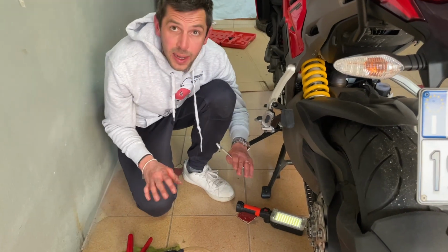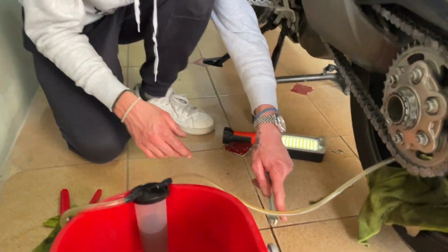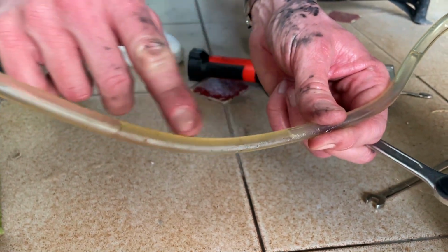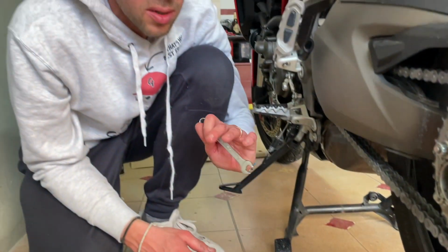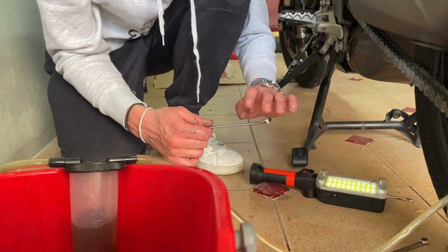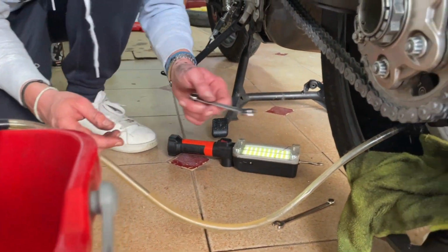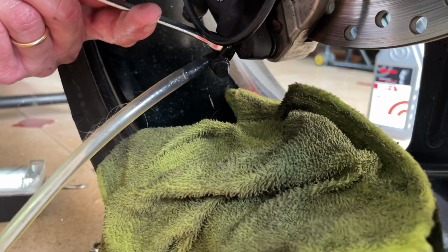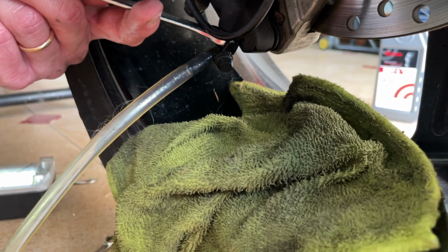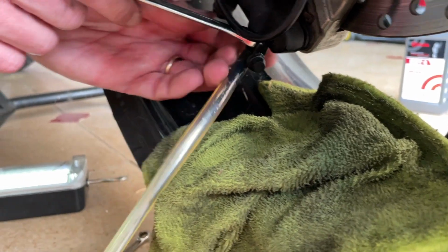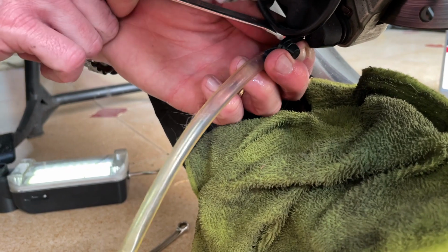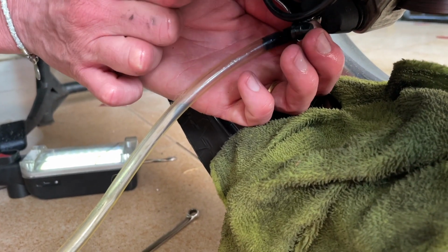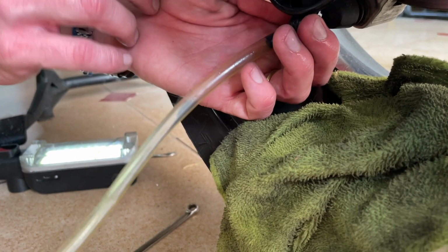Now let's have the final touch. We bled all the system, so as you can see, the oil in the pipe is the new one, so it means that we have flushed the entire system. And now for the final touch, just to secure all the bubbles are out, we will do something like that. We will close the valve, create some vacuum, and then once we have the vacuum, just release a bit, and then once we have no more vacuum, we close the oil.